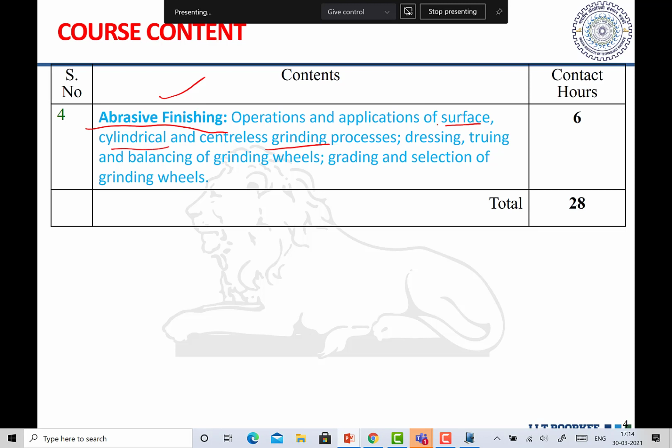And when the grinding wheel is used, we find that the grinding wheel goes out of shape. So this has to be balanced, because the grinding wheel is rotating at a high speed of, say, 2000-3000 rpm with a very heavy mass. When it becomes imbalanced, there is a huge possibility of fracture of the grinding wheel. Whenever the grinding wheel fractures, all the broken parts come out like a bullet and damage man and machine. So a lot of undesirable things can happen.